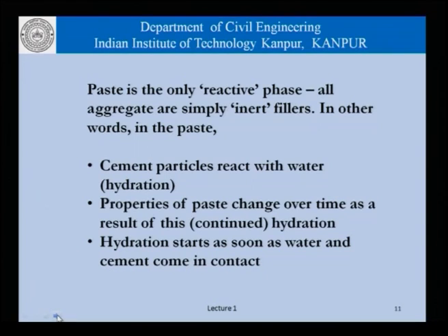In other words, paste is the only reactive phase. All other aggregates, whether sand or coarse aggregates, are simply inert fillers, which means that cement particles react with water, as we have said. The properties of cement paste change over time as a result of this continued hydration, and hydration starts as soon as water and cement come in contact.